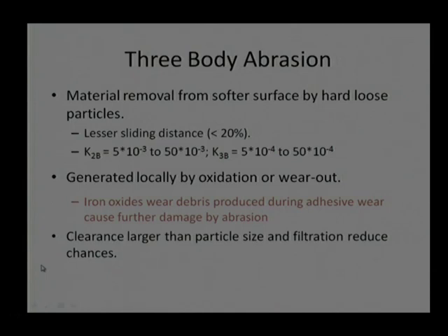The interesting thing is that if the clearance between two surfaces is larger than the particle size, then this third body abrasion will not cause much damage. In other words, if we know the particle size which is getting generated between the two surfaces of one pair, then we should keep the clearance in such a manner that the particles which are interposed between the two surfaces are not going to cause much failure.